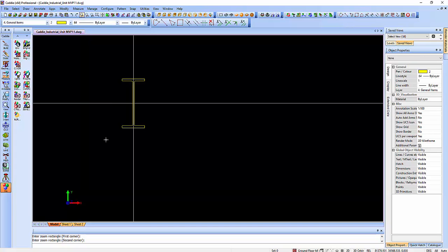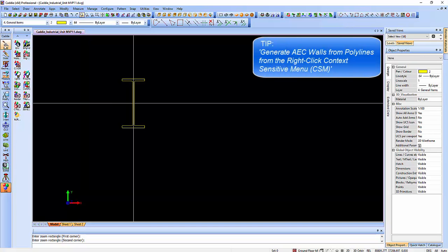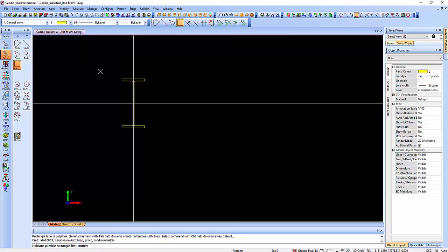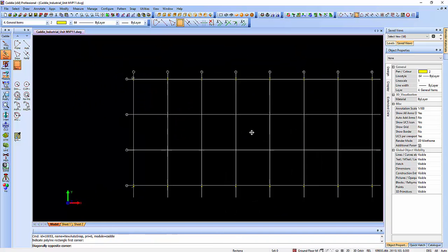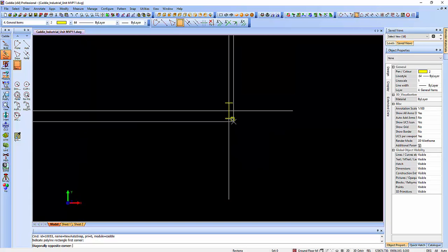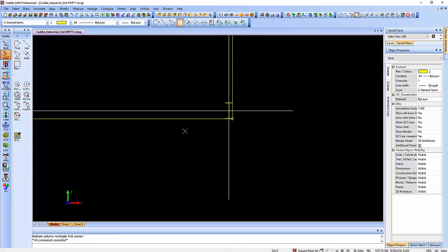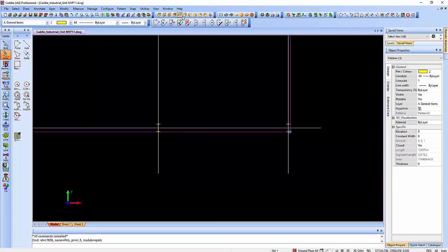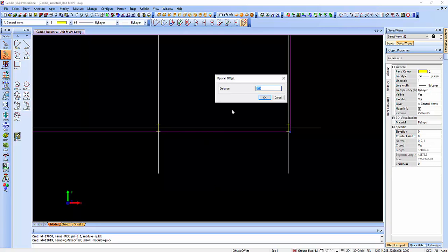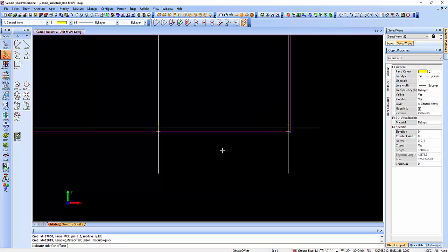We're going to do these from Polylines, so we could go to the build commands, the draw command and so on. But if I just go to something as simple as a Polyline, so we'll just choose Auto Snap, pick on the corner there, drag down to the other corner, place our Polyline in. Now, there's our Polyline. Under the context toolbar we have offsets, so I know that I need an offset of 135 till we get to the cladding, so purlin will be and so on, so OK that.